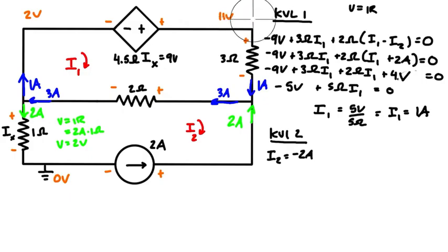So we're going to go from 11 volts down to 8 volts here. So this node has a voltage that is 8 volts higher than ground. Okay, so now we have the voltage at each node, and let's just make sure we know the drop across everything. So in the bottom left, the resistor here, the voltage drop is 2 volts.